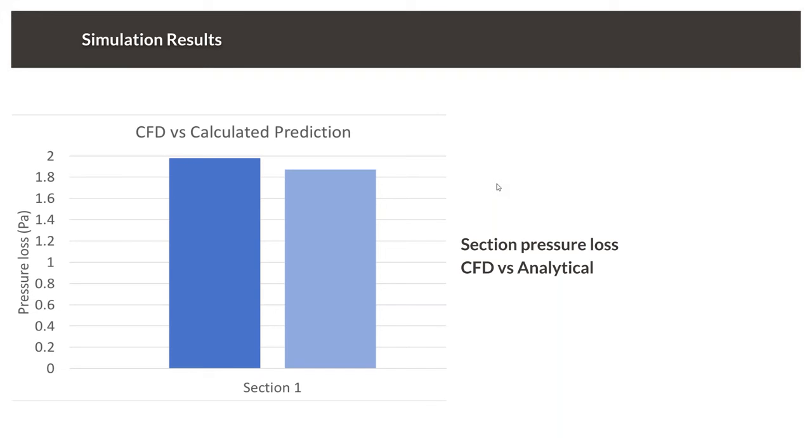And you will say maybe, well, 10%, why should I care? Well, a lot of times it's maybe not important, but whenever you have big changes, for example pressure separations, this is something which cannot be predicted very well by analytical models. And so CFD is not only adding more precision, but also allows you to understand what is happening inside the flow.